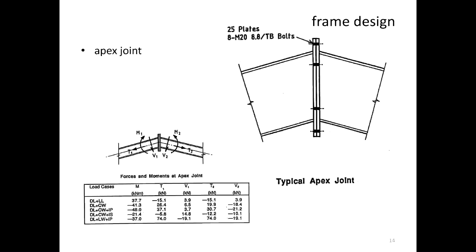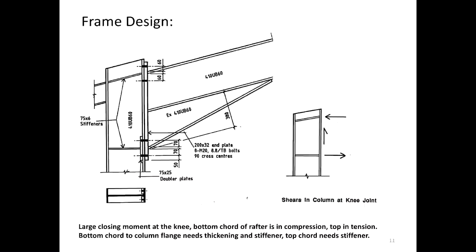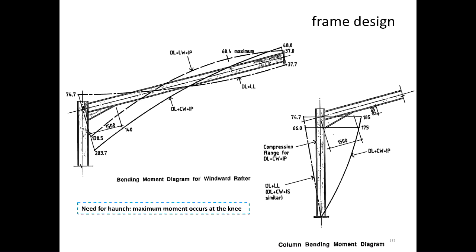So what will happen if I go back to my bending moment diagram? Here, I've got the bending. Somewhere around, I've got another bending here. This is the governing one, which means this will be maximum. So around that area would be the best point to put my bolted splice, where I have very close to 0 bending moment.